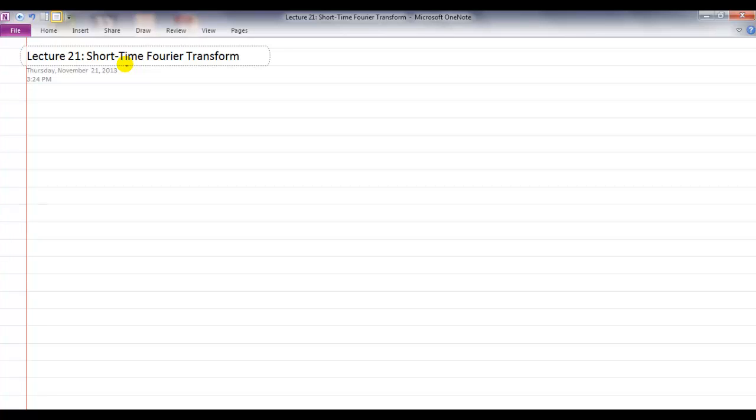Now, we had briefly talked about the trade-off between time and frequency resolution. The idea of time resolution is pretty clear from the motivation of the short-time Fourier transform, which is that the longer your window is, the harder it will be for you to tell when a signal starts. So that is pretty obvious. Let's now take a formal view of why having a longer window is necessary for getting good frequency resolution. To remind ourselves, the short-time Fourier transform definition is a function of two variables.